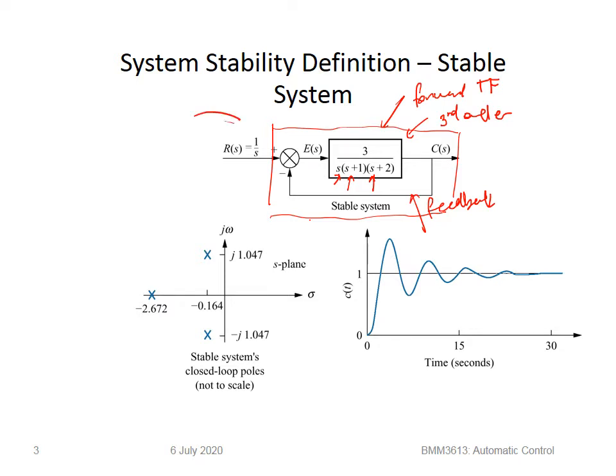If I can write over here, the equivalent transfer function, let's say I'll call it G(s), has the same input R(s) and same output C(s). So what you need to do is simplify this transfer function. How do we simplify it? We have learned in the first part of the second chapter of analysis of system. Basically, for G(s), let's say we call this transfer function G1(s).